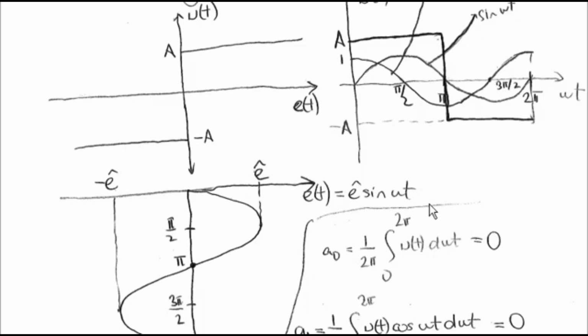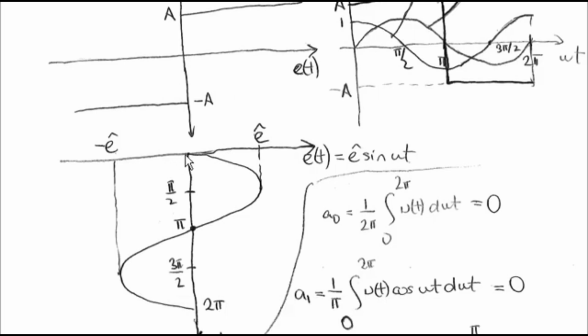And the reason for this is that this nonlinearity here, the relay nonlinearity, is an odd function. So it satisfies the odd function property, and we know that for every positive input value, there is a corresponding negative input value which has the opposite sign. Therefore, this integral would always cancel when this nonlinearity is an odd function.